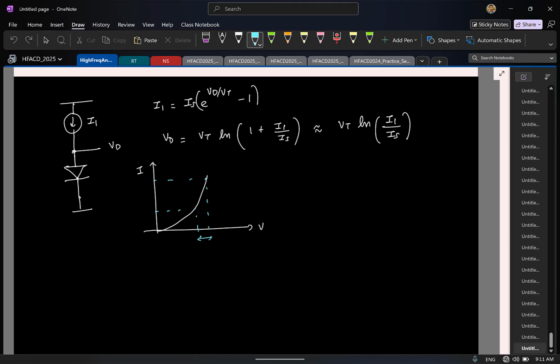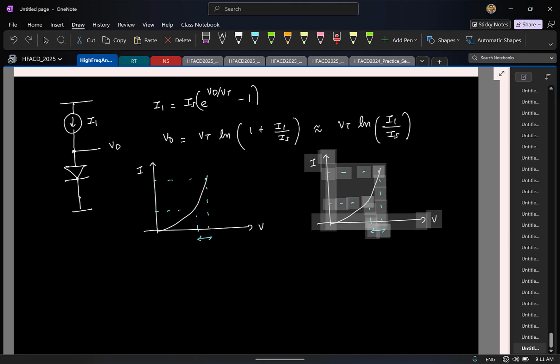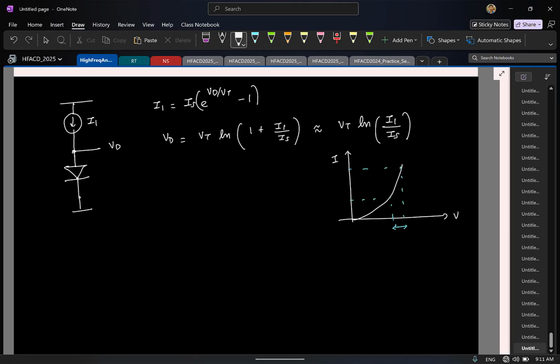So now, one quick digression. It turns out in many CMOS processes, it is not possible to get an isolated diode because of the following reason. Remember, in a CMOS process we have a common P substrate. And typically, where is this common P substrate connected to? Remember, this is the body terminal of all NMOS transistors. We connect it to ground.